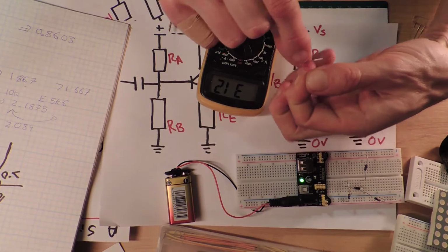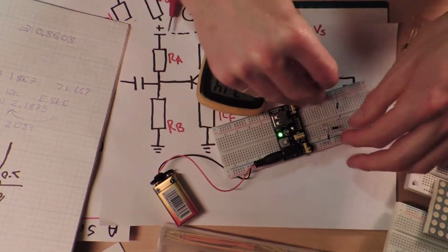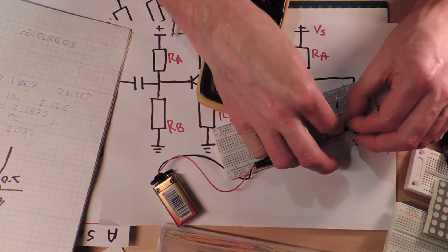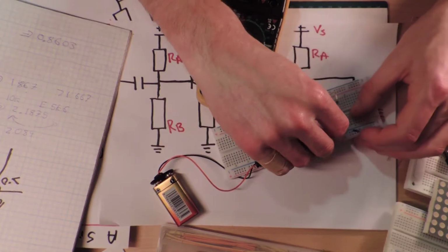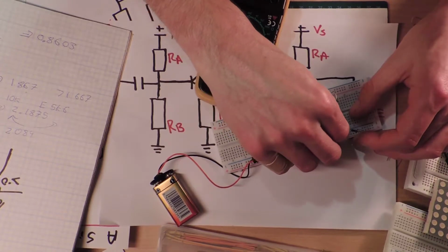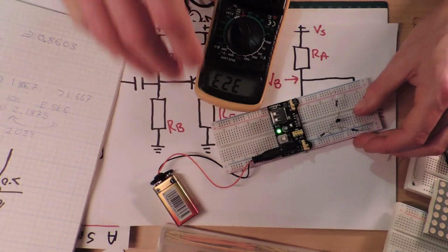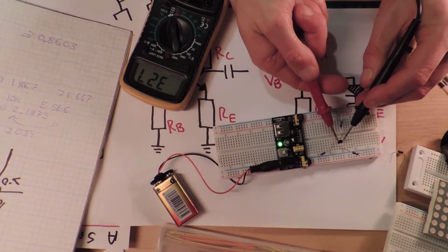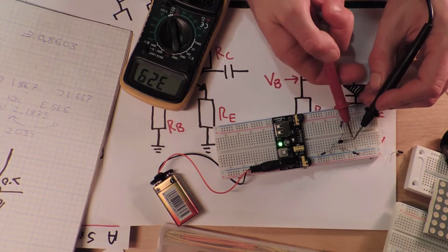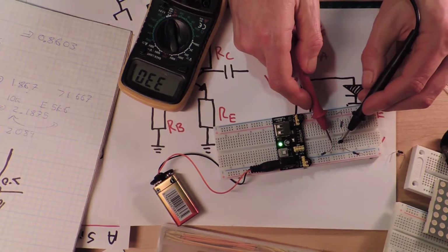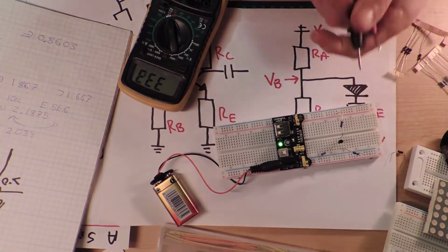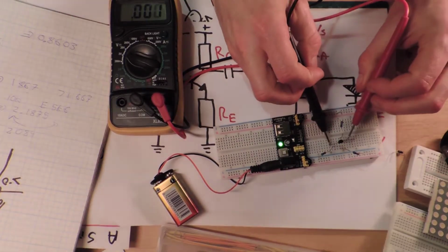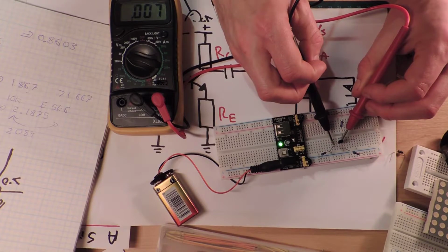Poor little transistor is going to have a bad day, and then we're going to take that out and replace it. I'm going to say why this doesn't actually work when you're using it as a transistor. But let's just see. That should act like a diode at the moment. So this is a little 2N2222, and I've taken away the collector leg, and I've just used the base to the emitter.